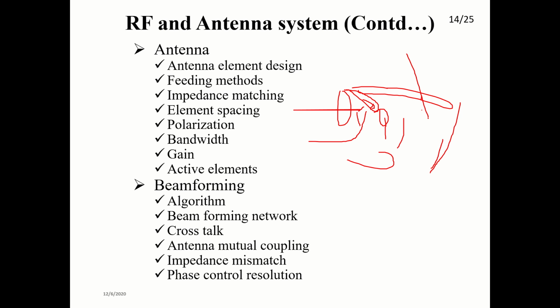So several things are coming into the picture. Next, diodes, and also varactor diodes, or PIN diodes for phase shifting, changing the excitation of the element design. The feed network takes care of this: we have to excite the element with a particular amplitude and phase so that you can achieve the beamwidth. I think I explained this in the previous lectures.